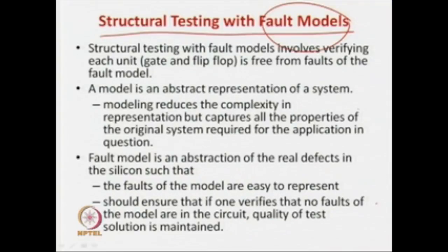We verify whether the AND gate is functionally correct, that is 0 0, 0 1, 1 0, 1 1. And in the case of a full adder, we have to verify whether it is doing the addition, whether the sum and carry out are proper or not. But if we go for structural testing with a fault model, we will even forget that an AND gate is an AND gate and a full adder is an adder.